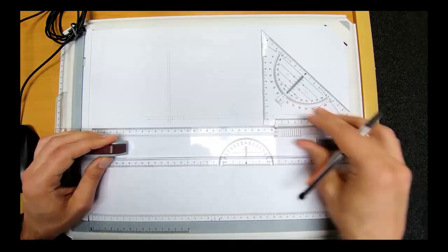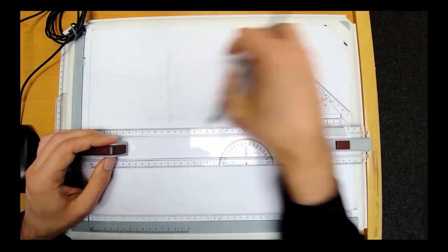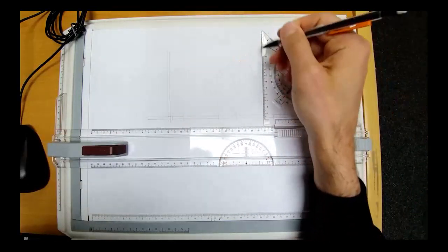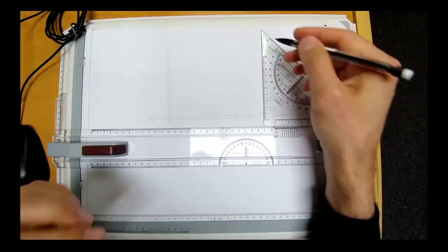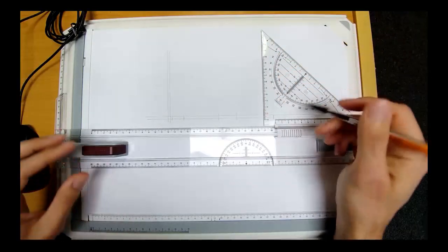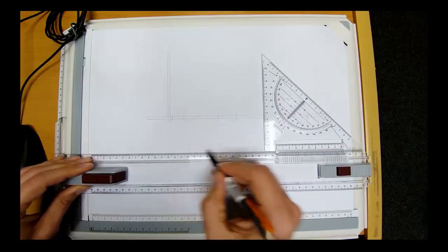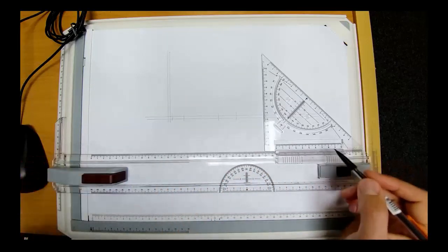And that's it. Basically, you're gonna start by doing all the four external walls. Then you can draw the internal walls for the toilet and the bedroom here. And then you can do the same for the columns, the 4 columns that we have.